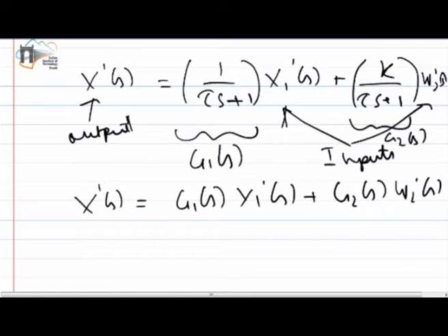So you see what you have understood from this, what we have done. We have a physical process, and we have tried to study the dynamics of the system. We need a mathematical representation of the physical process, and compute the transfer function of the model. This is a first order system, because the denominator has only one power of s, the maximum power of s. Here you will see that we have a linear system already.